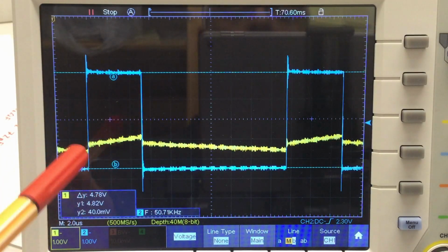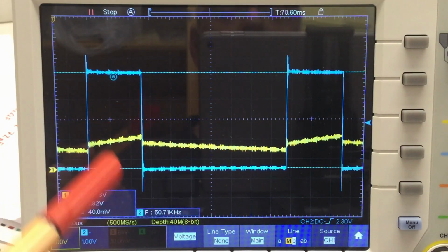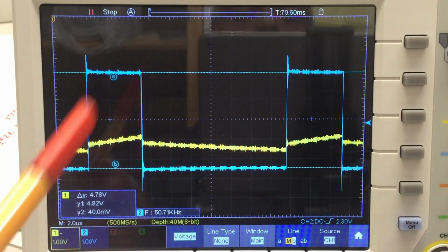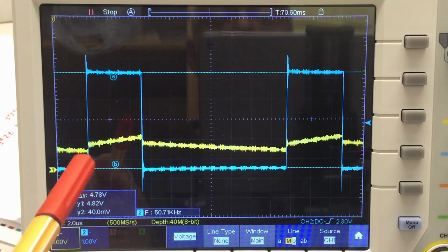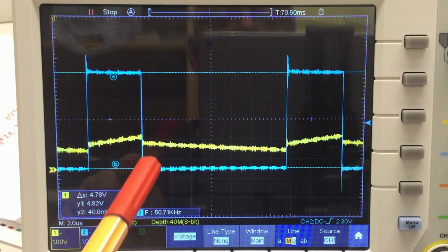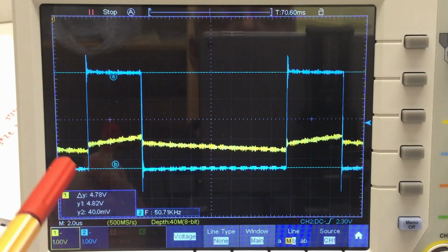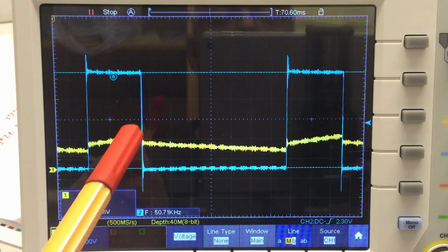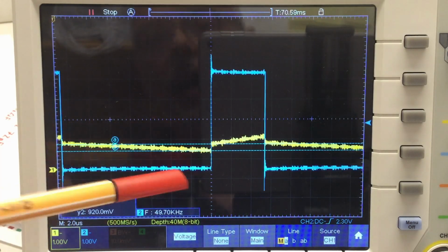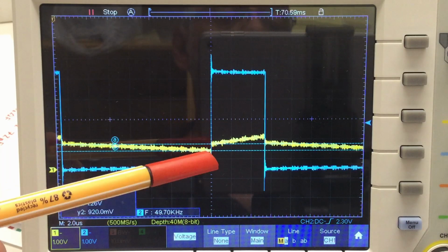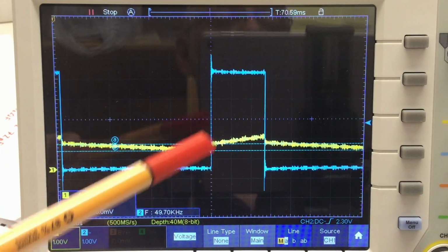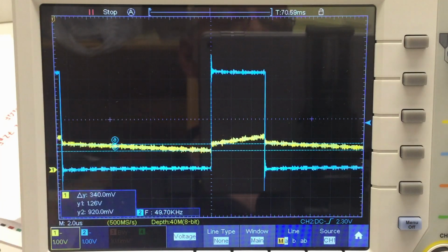As I mentioned before, that shouldn't really influence or mess up our nice relationship between frequency and capacity. But as you can see, at the beginning of the charging and at the beginning of the discharging, we have these jumps, and these are a problem. With the dry sensor, we see a jump of about 340 millivolts when we start charging.